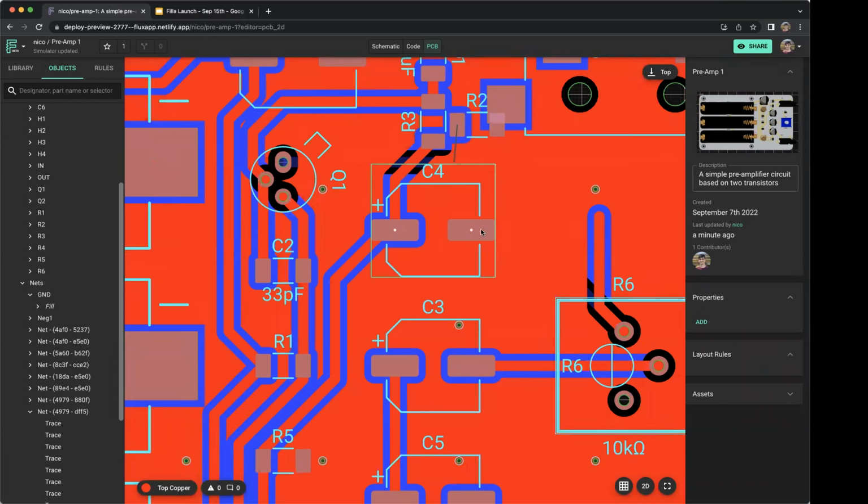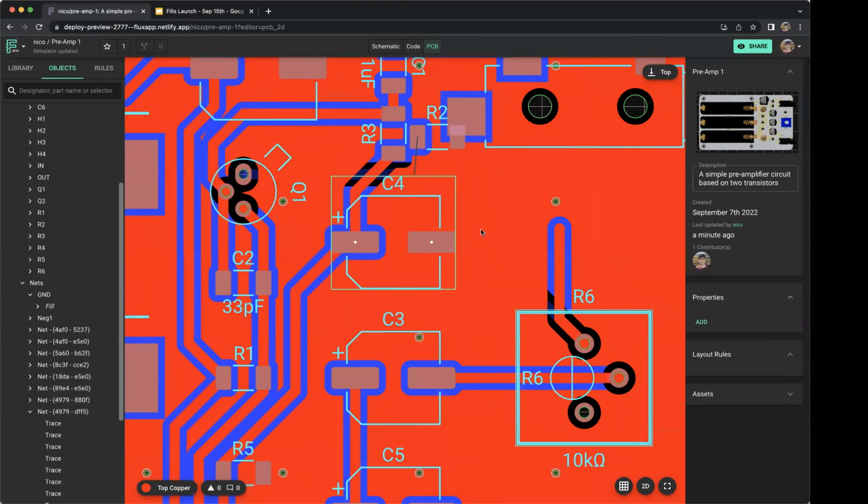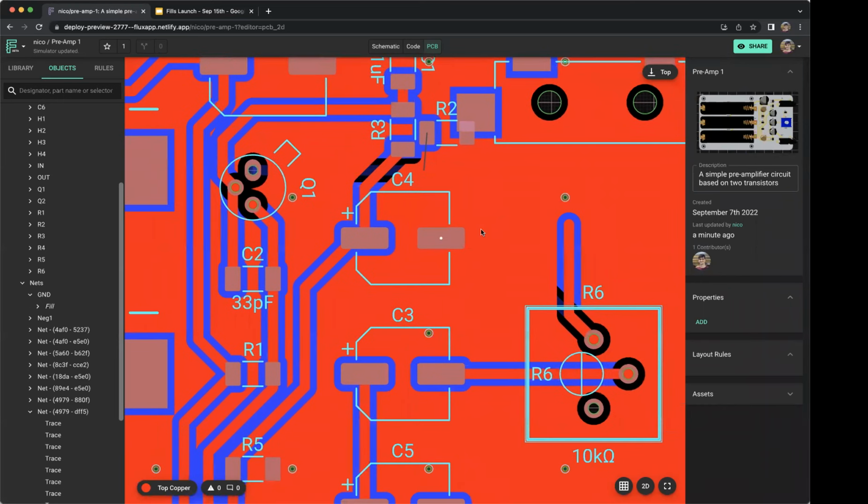I have had some issues with my design, basically on a hobby project, and I don't see any thermal reliefs or copper spokes on this pin. So it's a huge plane, and it has a big thermal mass. If I do soldering on a hobby project, it's a big pain. So do you have such a plane for this?